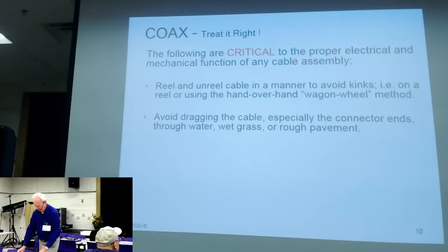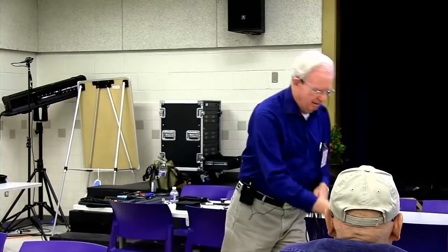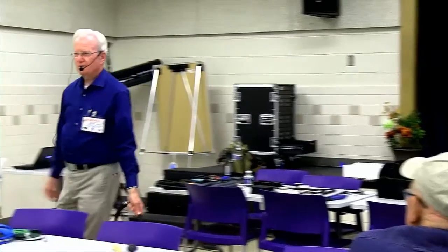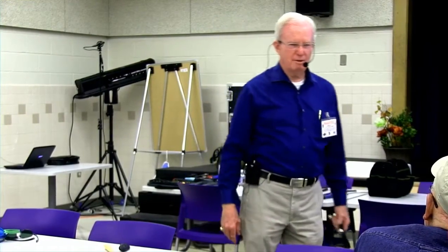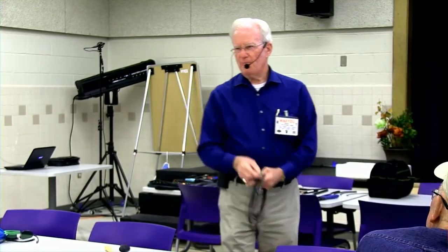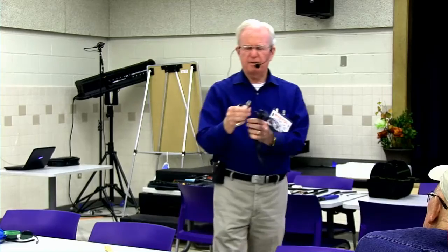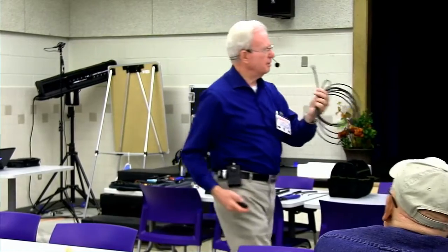Oh, how about this one? Oh, I love this one. I used to have my students go to Bull Run Park. Nice wet morning grass, and they'd pull the connector right through the grass, hook it up to the radio, and the SWR is 63-1, right? Mr. Payne, we have a problem with the cable. I then have them take this off and go, and they get a mouthful of water. So guys, keep it off concrete also. Don't drag it across concrete. Have a lot of respect for your connectors, please.